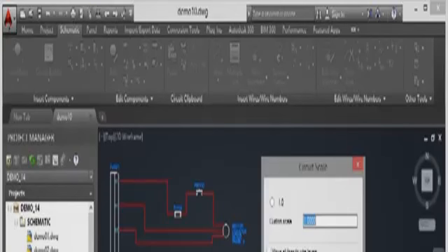What I can also do is move all lines to wire layers, keep all fixed wire numbers, keep all source arrows, update the circuit's text layers as required. That's very useful, because then it all comes in on the right layers in the current drawing here. And also, you can say not to blank out any orphaned contacts. Sometimes you might need those and you might need to bring them back into the AutoCAD Electrical Project database at a later date, so you might not want to blank them out.